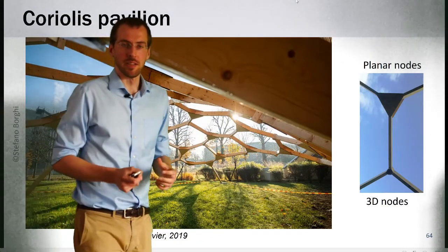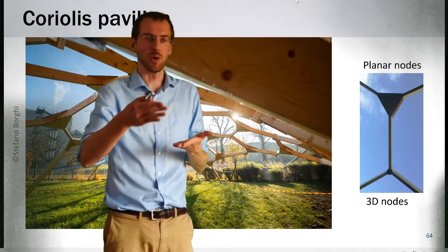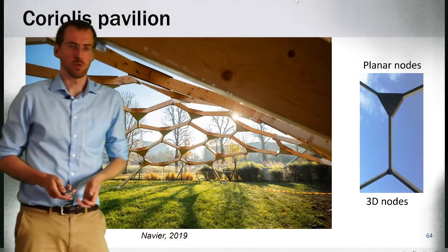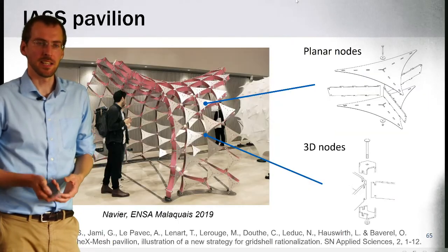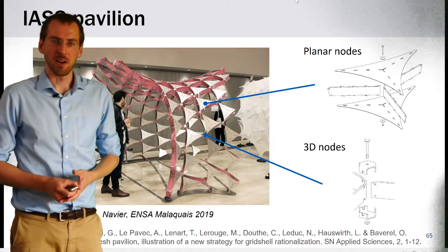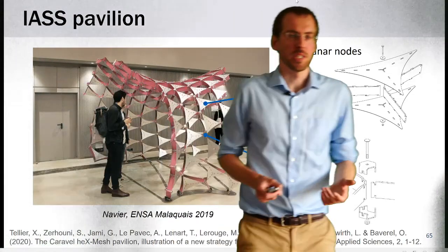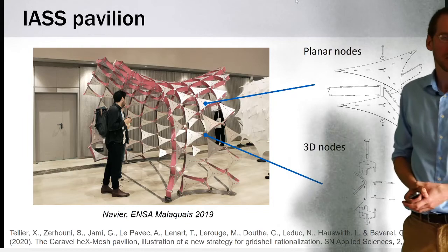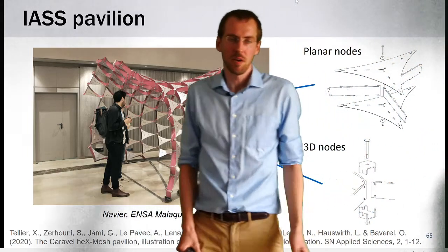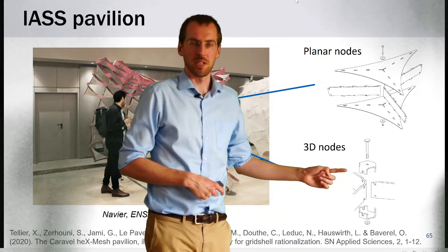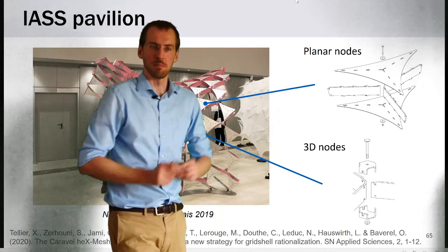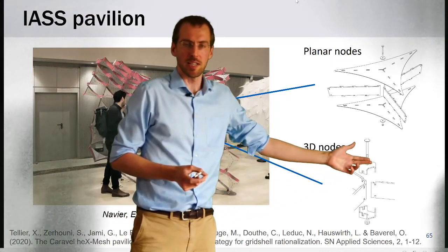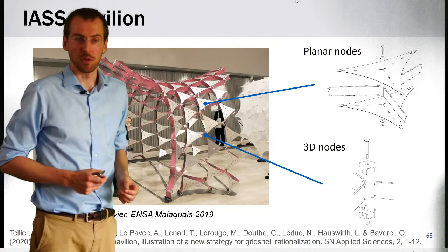And then if you look at all the other beams, you actually just need a circular saw, and you can cut everything with just one angle. You don't need complex 2D cuttings to get the beams into shape. Here is another example made of steel and aluminum panels, in which we use these properties to get something that can be built entirely from laser cut elements or with 3-axis milling systems. The only element that cannot be built with laser cutting and needs more transformation is this 3D node, which is a stamped piece of steel. But for this element, you can just mass produce the nodes as they are all identical throughout the entire structure.